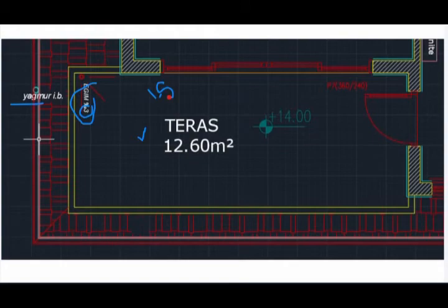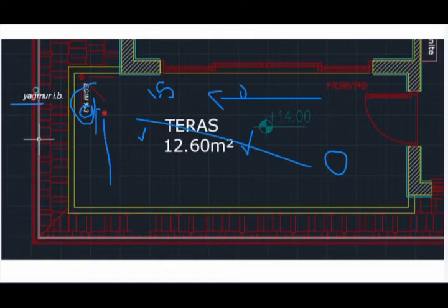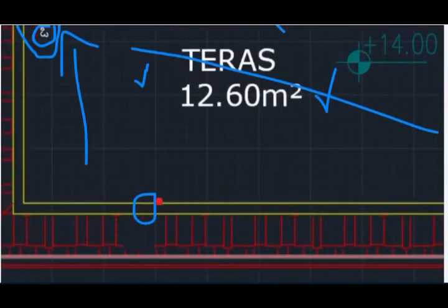And the reason is that you will see they are not working perfectly with that slope. If you wash this balcony, half of the water will stay here, half of the water will stay in this part. But if you create a nice slope, automatically the water will go. So this is 2-line. And what is the reason that we have 2-line in the balcony?